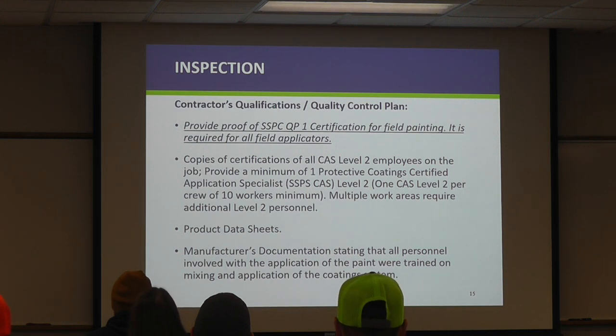Let's see, SSPC QP 1 is often overlooked or missed by just about everybody. It's a requirement for all field applicators. It provides documentation showing that the applicators, the people in the field working for the painting company, actually know what they're doing, that they've been trained using the specific coating system that you're going to be applying.